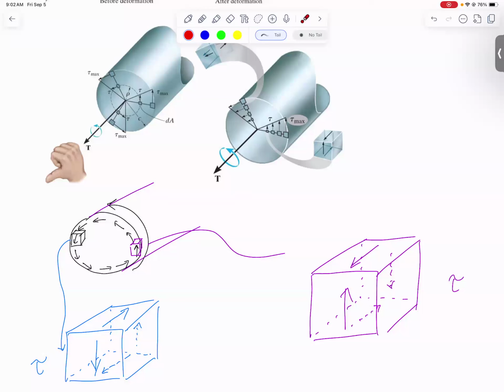And that's actually caused by the shear stress that ends up happening not on that cut open circular face, but in the longitudinal direction because of the fact that these little cubes have to be in equilibrium. That's what these pictures are trying to show in part. If I come right here and I zoom in, I'm going to get a little cube that's going to have a stress on the front face that matches that direction, and then an induced stress on the top and bottom faces so that this cube will be in equilibrium, and that's the picture I drew right here.